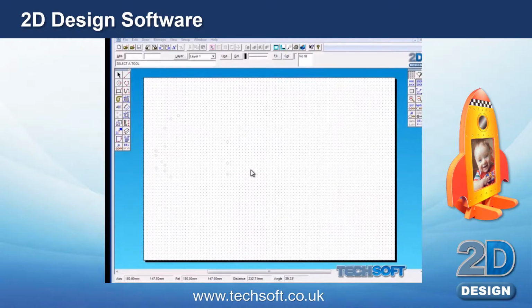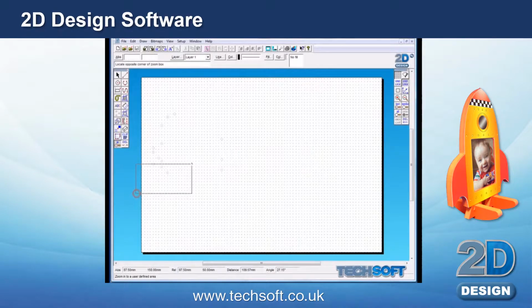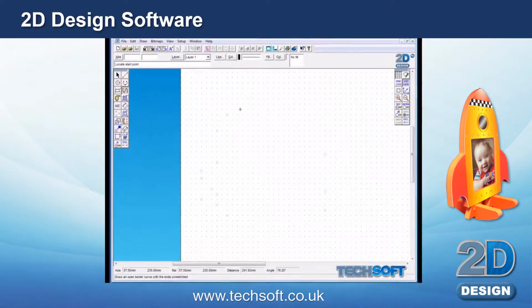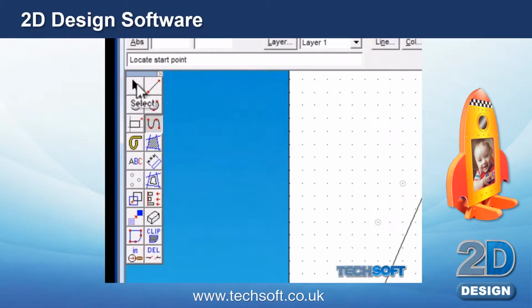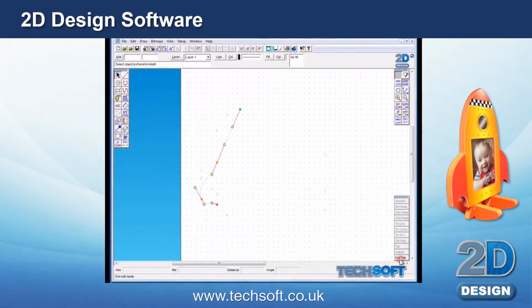To start with, we're going to draw half the rocket shape. We'll just zoom in. We'll use the path tool and we're going to click on the construction point to make this curve. You right click to complete it. You'll then need to select that line using the select tool. You go to start edit and you can move these nodes over to the construction point. You'll notice this just moves the line around.